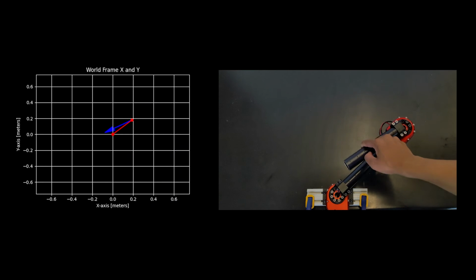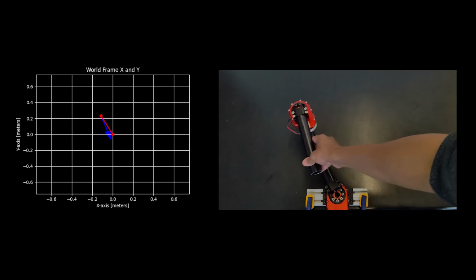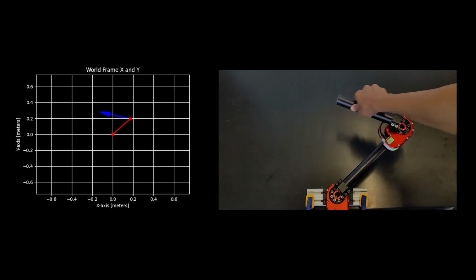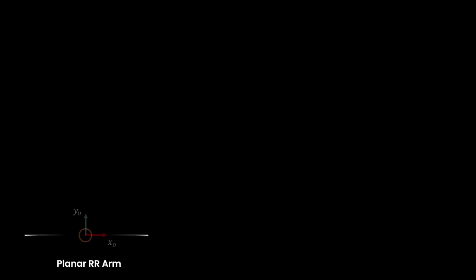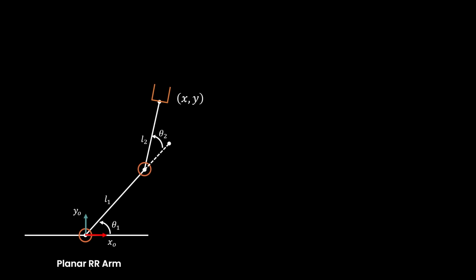The main reason for learning all these rigid body motion transforms is for easier representation when doing forward kinematics. Forward kinematics is the process of going from robot joint space, or the motion of the joints of the manipulator, to the task space, or where the end effector will be in the world. One of the simplest cases is the planar 2 degree of freedom open chain arm with known link lengths. The number of joints of the manipulator determines the degrees of freedom of an open chain manipulator.